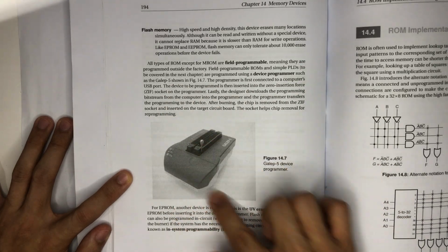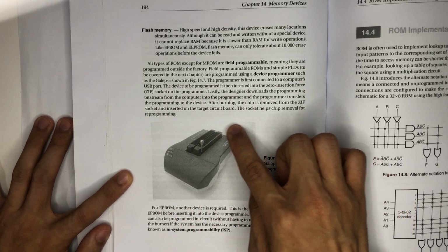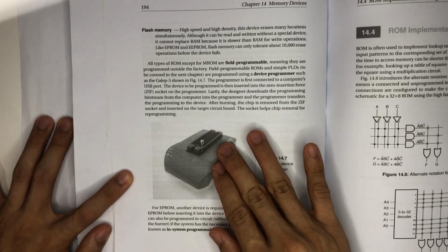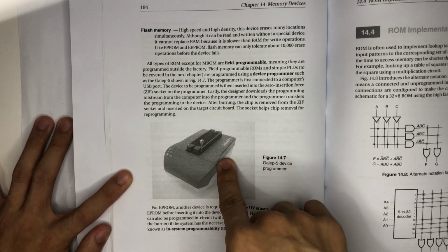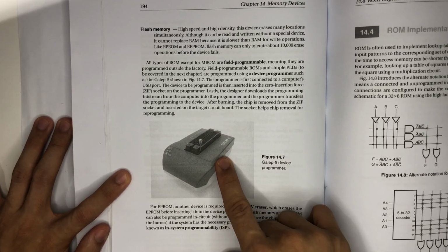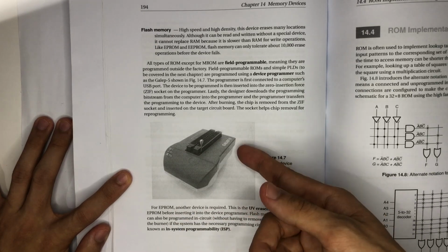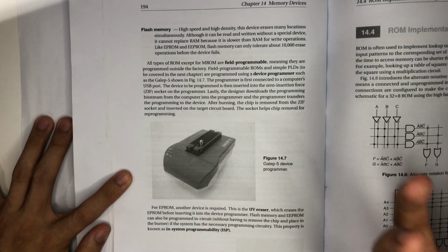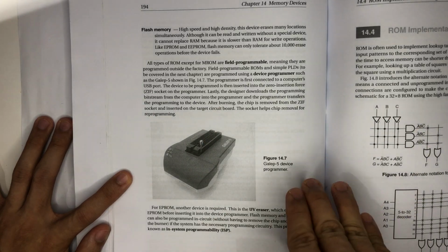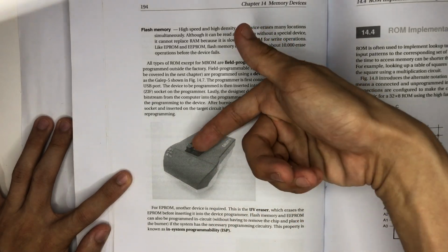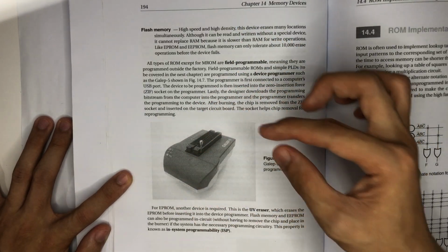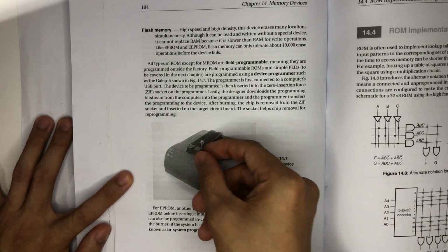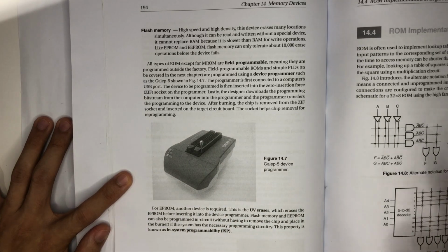So this is how we used to program a ROM. I think I was exposed to this during my degree. I saw it and we learned how to burn it. We use the word burning. Burning means that we want to program the chip. So we burn it. You put the chip on top of here. If you know, the chip has its legs, right? So you put it on here and then we lock them. You see the lock here, and then when we finish, we unlock, then we take it out. That means the chip is already burned.